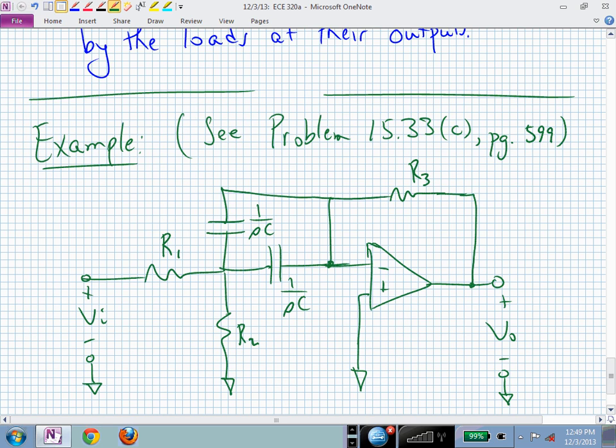And one thing, first, is there negative feedback? Yes, you are feeding the output back to the inverting terminal, and that's a good thing. That now makes this op amp have well-behaved properties if you don't drive it too hard or hit the extremes. What you want to maybe keep in mind is that that's now just a big node. You really sort of have two capacitors in parallel going in between those two resistors, and you have a feedback resistor coming back around that op amp.